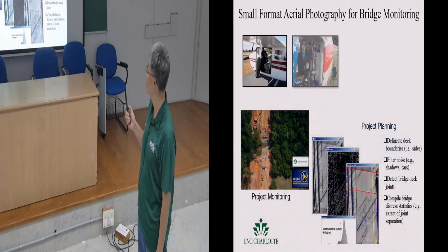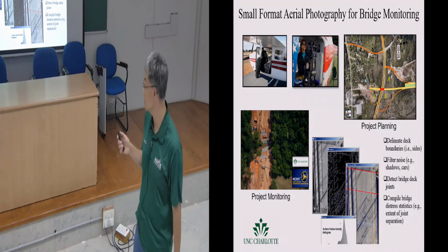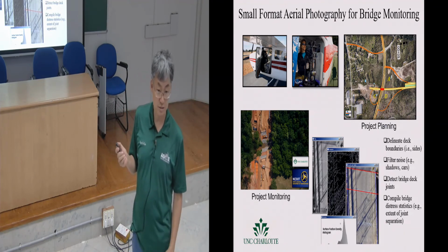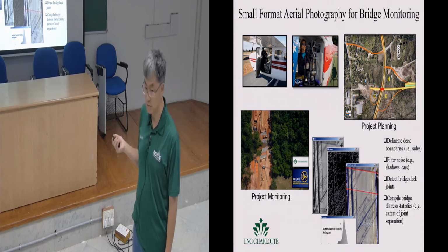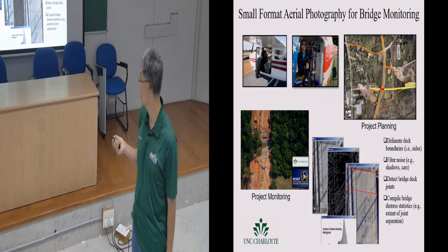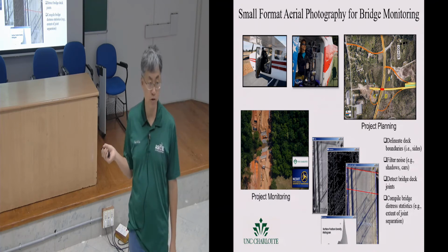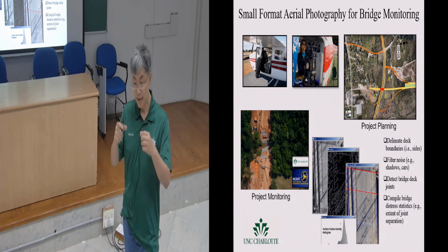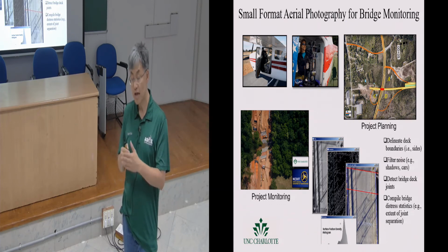It's challenging. Okay, and next is another technique that is specialized. I actually have a patent on this technique, which is to use small airplanes. Again, this is pre-drone days. We use high-speed cameras or regular cameras, and we were able to take aerial images. You can do a lot of monitoring. In this case, for example, we can monitor project development. The value of what we do is that we use a GPS camera, so every picture you take on the airplane is geo-referenced. Then we take that picture and put it in ArcGIS, and with GIS we can measure damage.